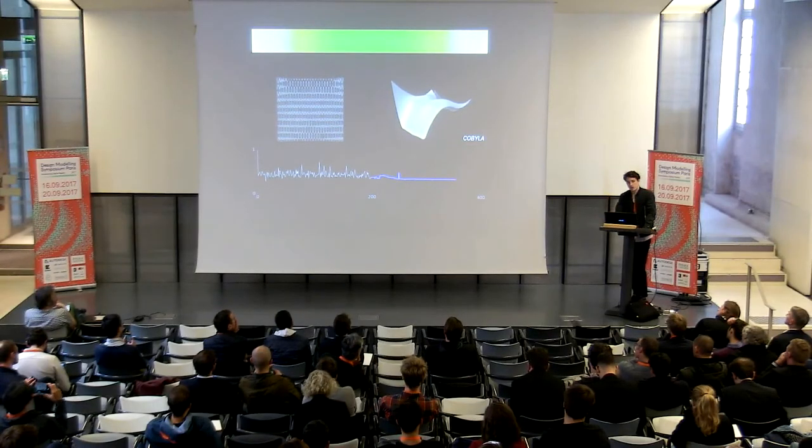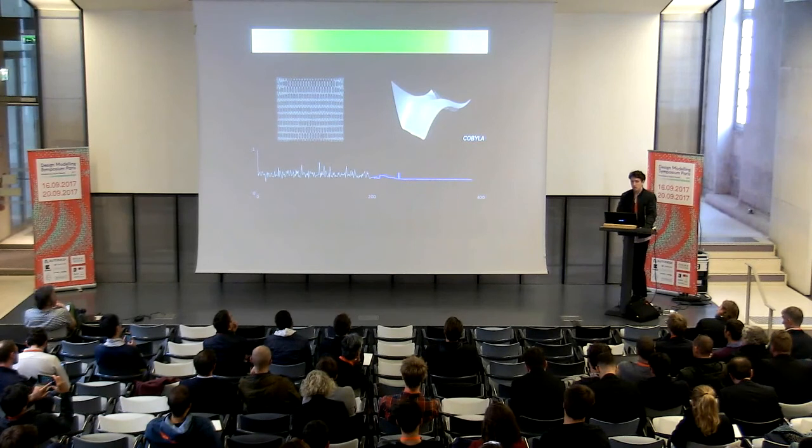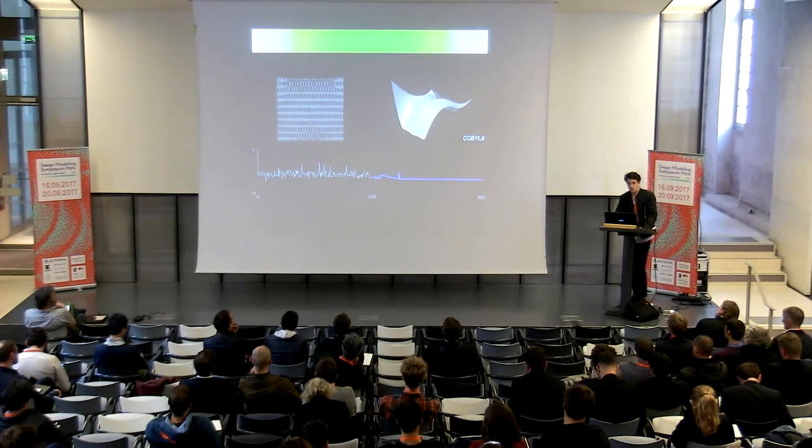So this video shows the prismatic beam simply supported, mapped with a triangular pattern, and optimized with a global scaling control surface on the right. And the beam deflection is indicated by an overlaid color map with white corresponding to zero displacement. Below, we can see the normalized strain energy shown decreasing as the algorithm progresses. In the first stage, we had a stochastic optimizer which searched the design space chaotically, and then the solution is finally optimized locally with a deterministic algorithm. And it converges to this result.